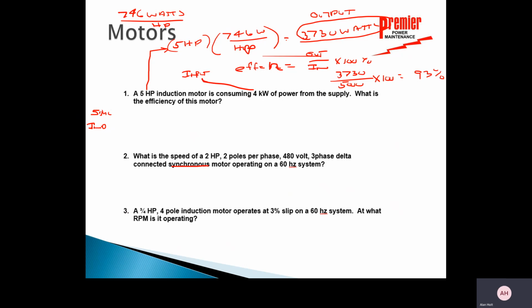In other words, that rotor is locked into that rotating magnetic field on the outside and cannot vary from whatever that rotating field speed is. An induction motor has to have the rotating magnetic field on the outside to create a magnetic field on the inside of that rotor.